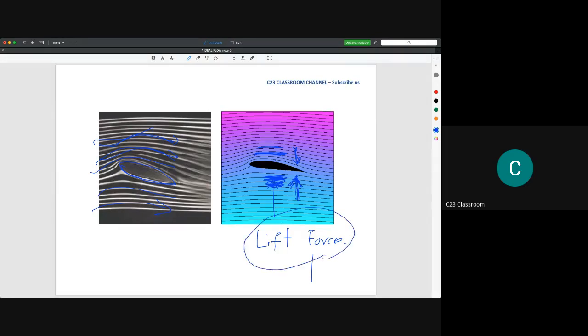So we purposely create the aerofoil to give us different regions of velocity. That's why normally we hope that the pressure at the bottom is greater compared with the pressure at the top, so the total force will go up. The upward force here is called a lift force. So this is the basic idea of how to fly an aeroplane.